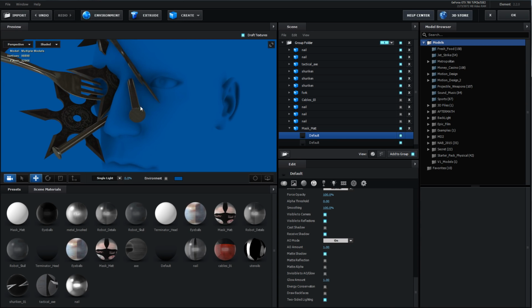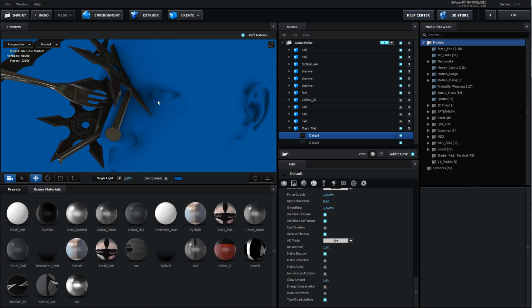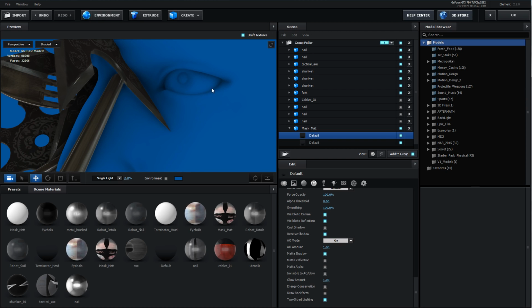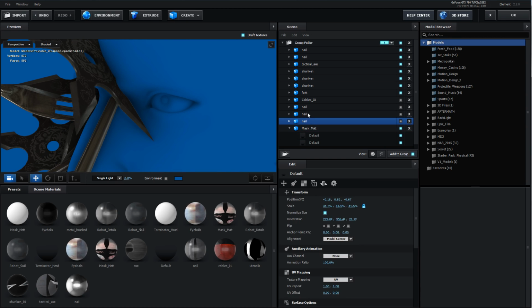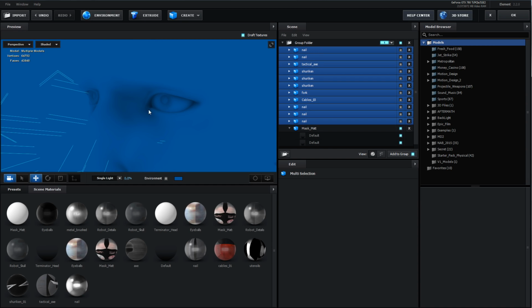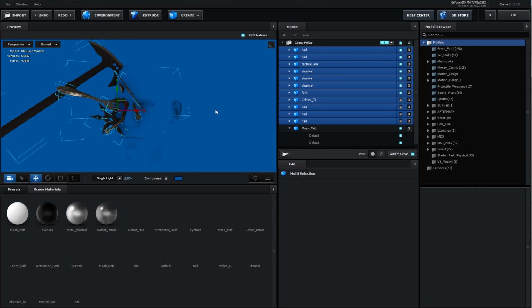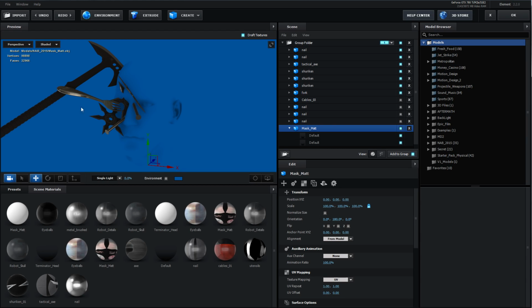And that way it receives the ambient occlusion and shadow. But the problem is it's generating ambient occlusion for itself. So even if I were to take all of these other objects and hide them, it's still creating ambient occlusion around the eyes, which is going to then add additional ambient occlusion where it doesn't need to be added. So the solution is we need the ambient occlusion to only be generated for the objects in relation to the face, but not the face on itself.